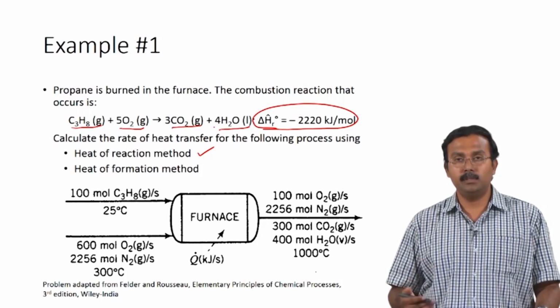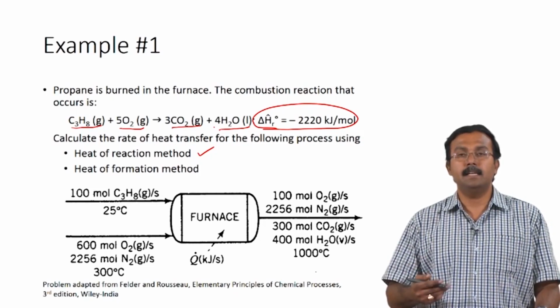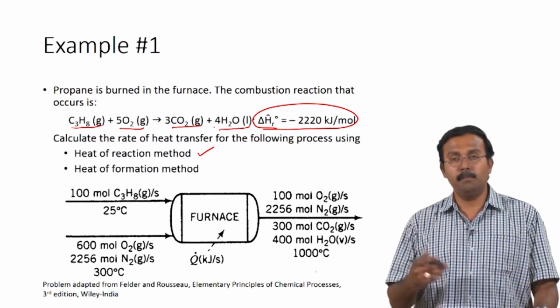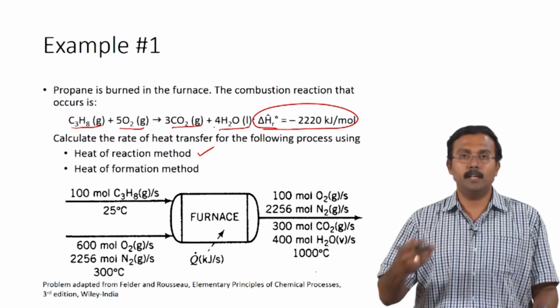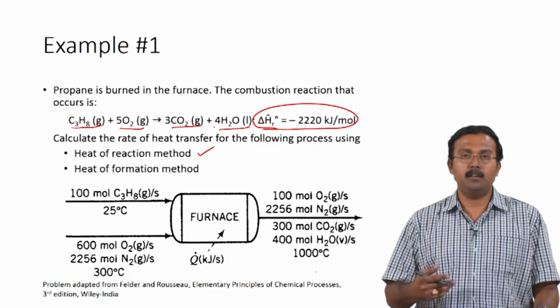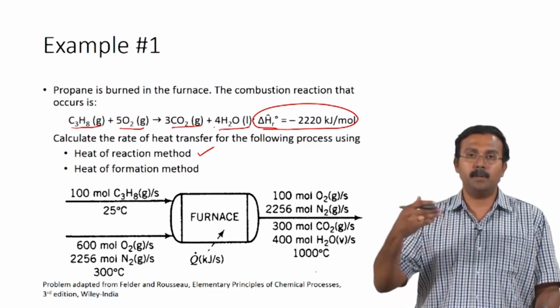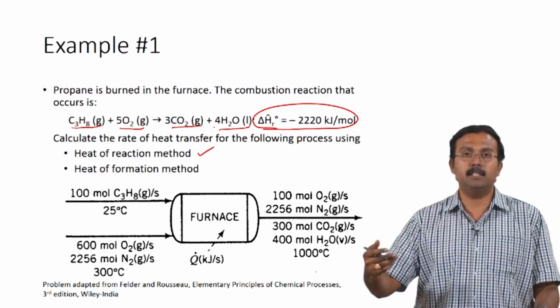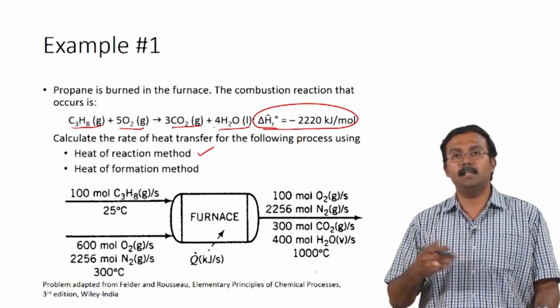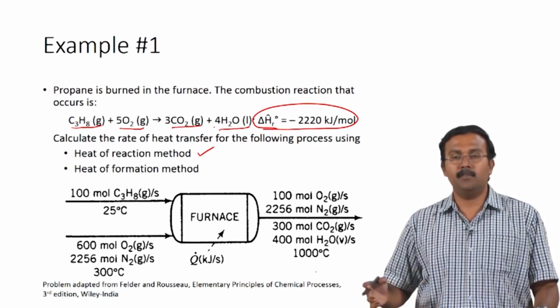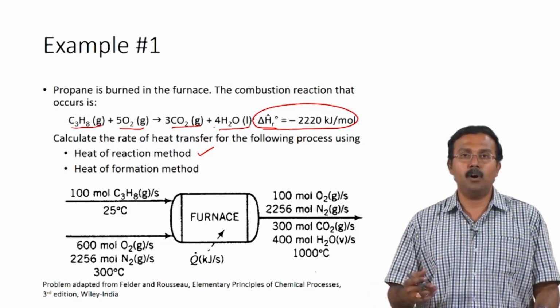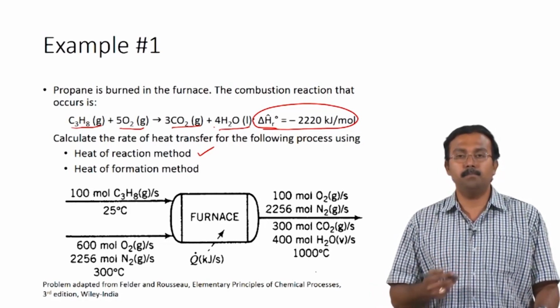and if you were to use that as the reference states, then you would be building the enthalpy table which would account for the heat of formation as part of the step where from the reference state of carbon and oxygen it goes to carbon dioxide, and then the next step would be where you have the heating. So, with this kind of a process you would account for the heat of reaction in an implicit way.